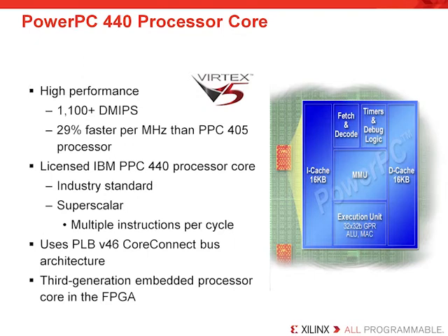There's also a dedicated JTAG chain as part of the PowerPC. Remember that the PowerPC is just an ASIC fused into the FPGA, so there are actually 2 JTAG chains, one for the PowerPC and one for the FPGA. When I say dedicated, I mean that the JTAG chain is separate from the programmable logic. As we'll see, one of the common questions customers have is how do I connect up the 2 JTAG chains to perform a configuration of the FPGA or to complete software debugging? Well, that's done with the JTAG PPC block component, and it allows you to add this JTAG component when you go through the Base System Builder.